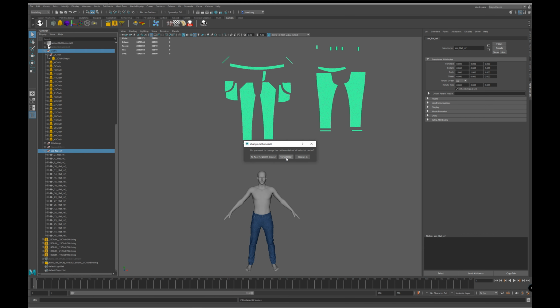For flat reference panels, we want the tailored model, so we can also control warp, weft and bias. If we are switching back to 3D drape panels for reference, then we would select the face segment crease model. So here we click on the tailored model button.